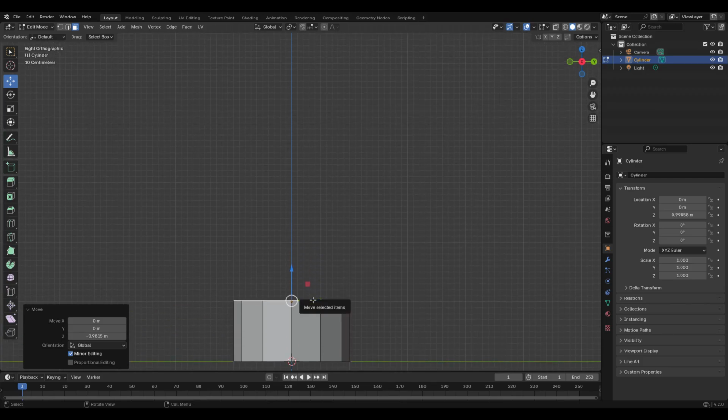So the average keg is going to have these two little rings around the center of it. The stainless steel ones, that is. So we're going to say probably about here will be our first ring. We'll say about there. So now we'll go over here. You can either hit E to extrude, or we can hit this little extrude button.